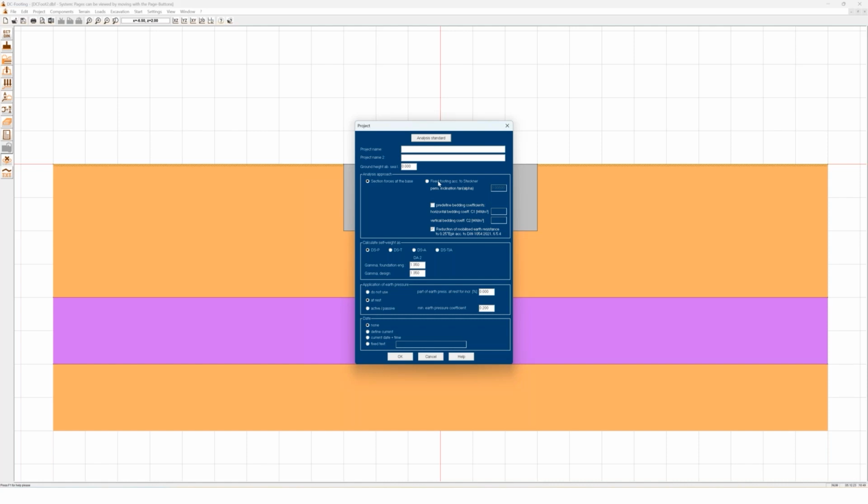It's DC pylon footing, which can calculate fixed blocks and pylon footings in accordance with the method by Steckner. It was published in 1989. This approach provides the serviceability and stability verifications for the pylon footings.